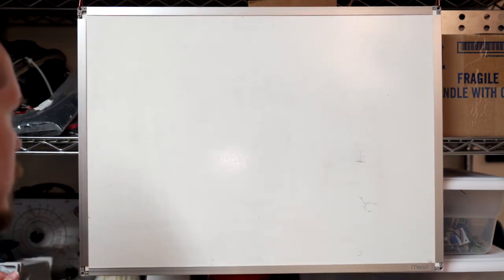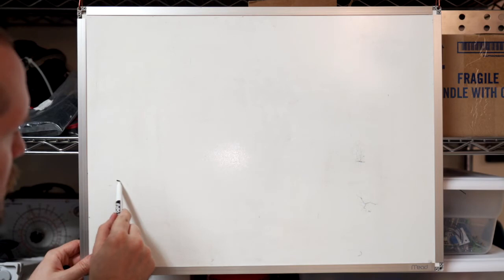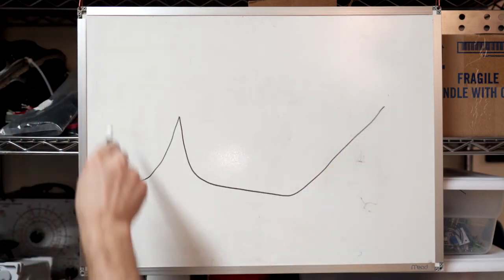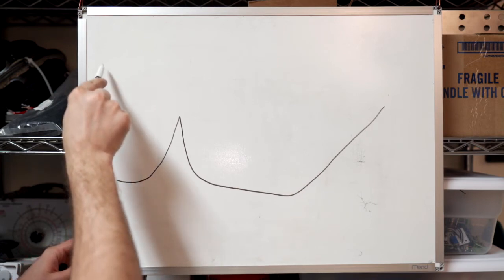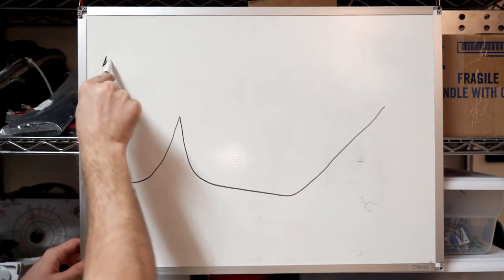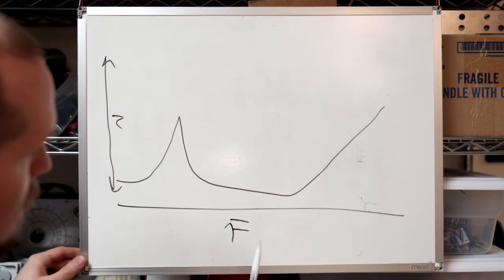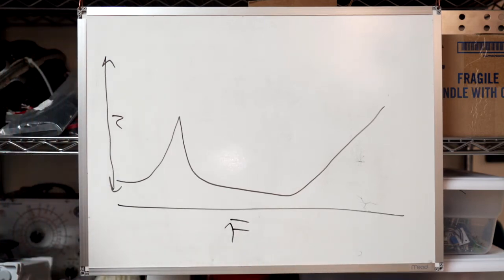They don't have that, so what they have is an impedance curve. Here we look at a typical impedance curve for a woofer. Over here we have impedance in this direction, that's Z, and down here we've got frequency. You can see that depending on the frequency that we're amplifying, we're going to have very different impedances in the second part of that voltage divider.